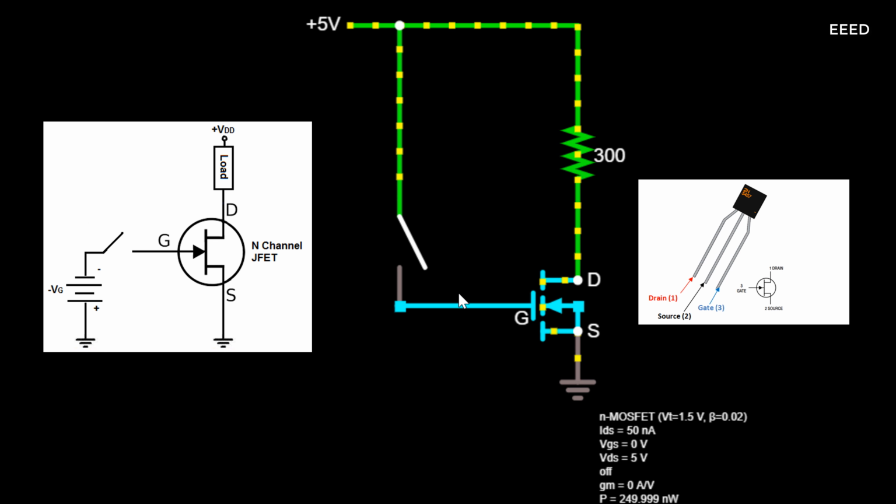If the gate voltage, VG, is 0V, the drain current is at its largest value for safe operation, and the JFET is in the on-active region. So with a sufficient positive voltage, VDD, and no voltage, 0V, applied to the gate, the N-channel JFET is in maximum operation and has the largest current.